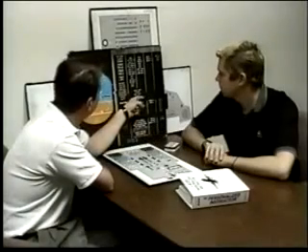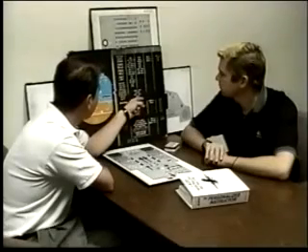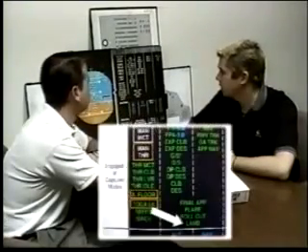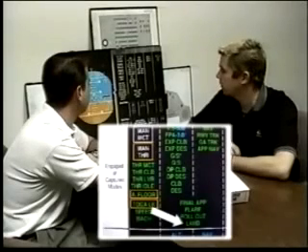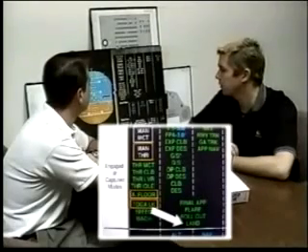Let's move back to both columns of the vertical and lateral modes, and let's start with the LAND FMA. Okay, LAND says that flare mode is ensured, and it occurs at 400 feet. During an auto-land approach, it can occur no later than 350 feet.